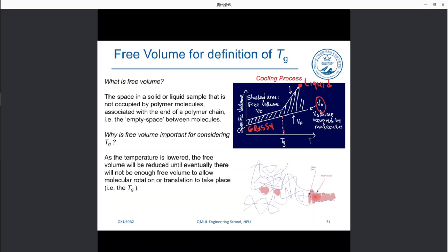When we reduce the thermal energy, there is a reduction in the movement of the chain, and until then free volume remains high. Once the chains get frozen, the free volume remains constant, and that is this region. Above the glass transition temperature we have an increase of the free volume because the chains are actually moving, and because they're moving we have more statistical opportunities to observe higher free volume.